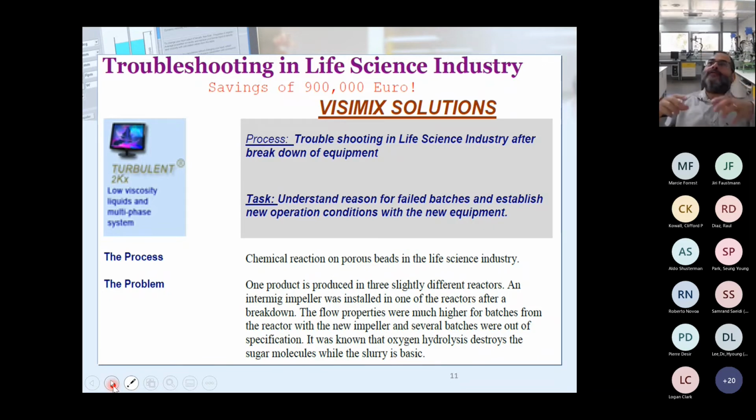But what happened when you have solids homogeneous in your new tank? Part of the solids see more oxygen from the headspace. And now you generate an impurity and hydrolysis and generate bad results. So here, the opposite: we thought that we need homogeneity because we're missing homogeneity. We designed for the solids because it was the main part of the process, but it generates bad results.